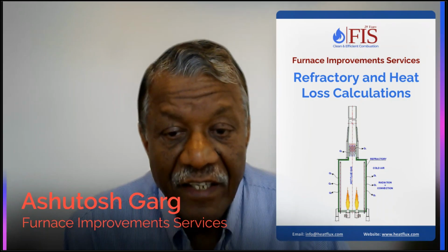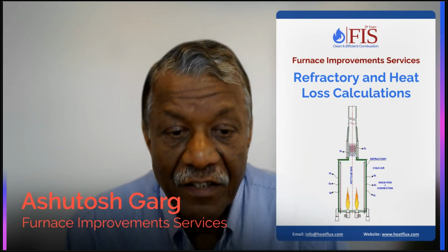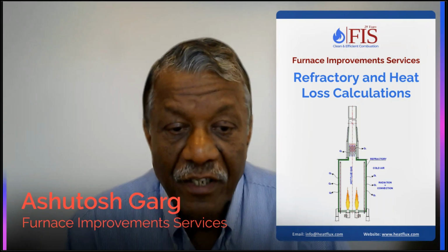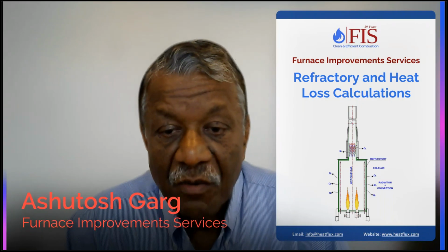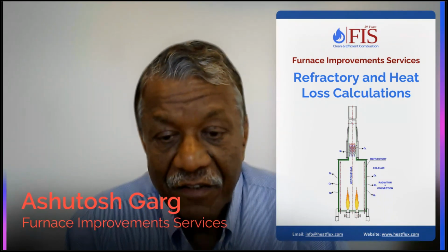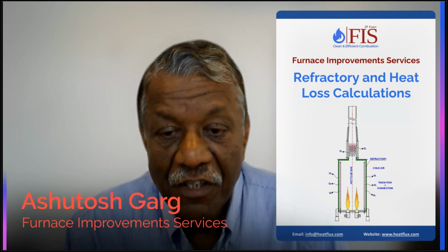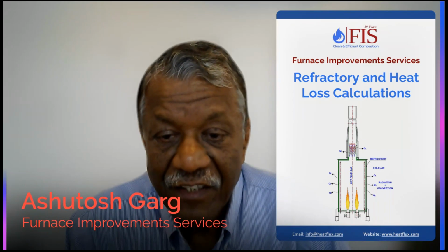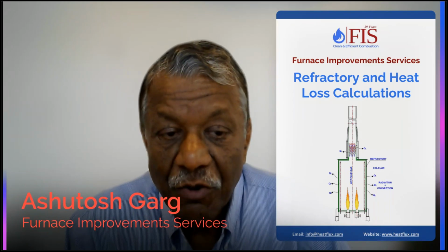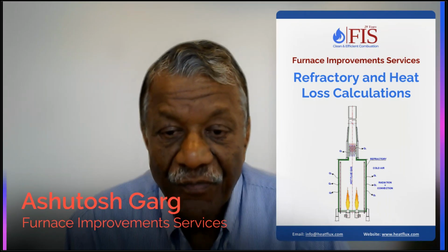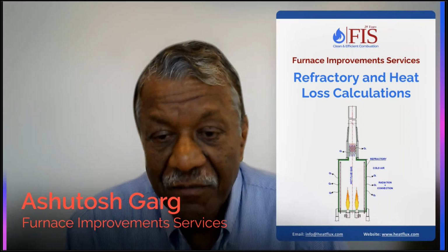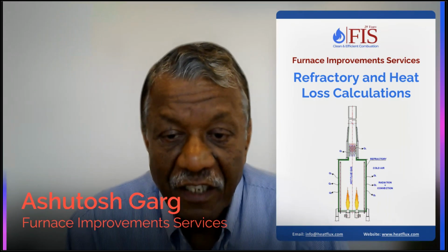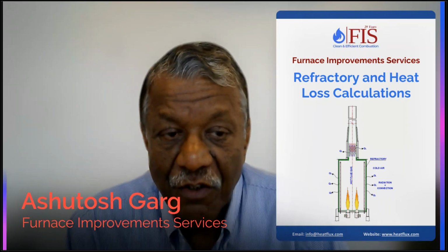Refractory lining in a fired heater is a very important component. Most of the people don't realize the importance of refractory because they are not able to see the function of refractory. But when you look at the radiant section, it has refractory. You look at the convection section, it has refractory corbels.